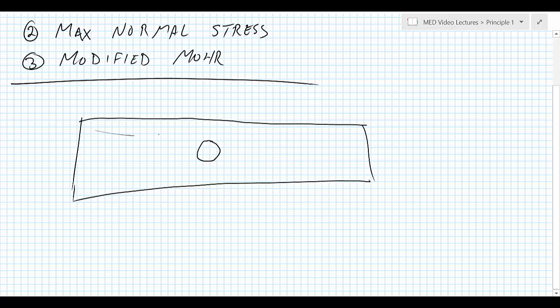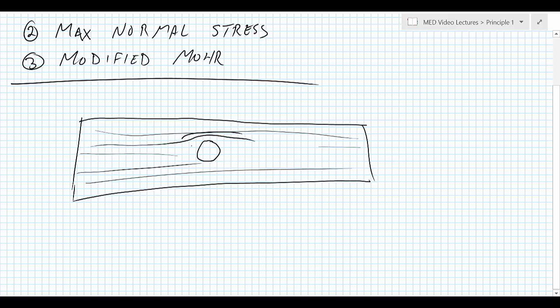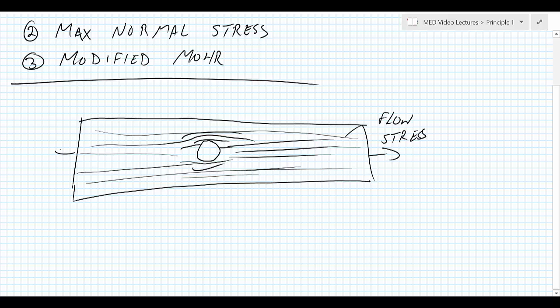If you imagine the water flowing down through this creek, hopefully you realize that there must be more flow lines around the discontinuity. These flow lines, in our analogy, are the flow of stress in the part when we put it under some force.